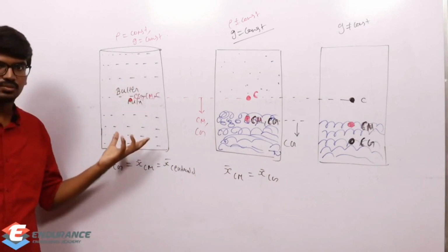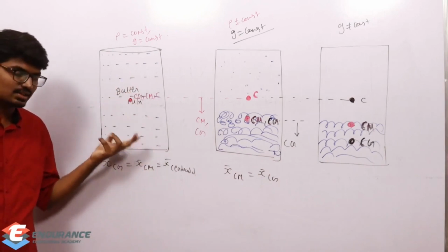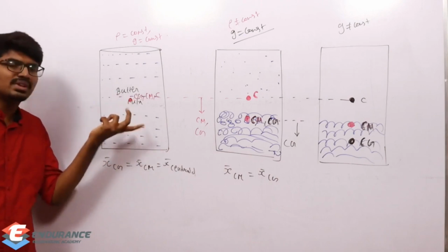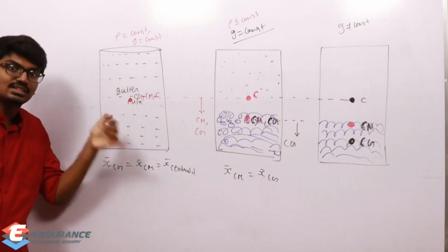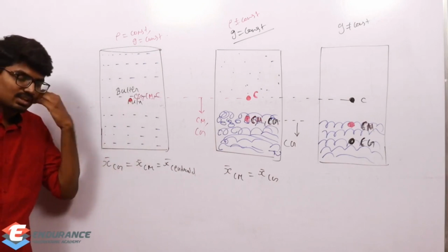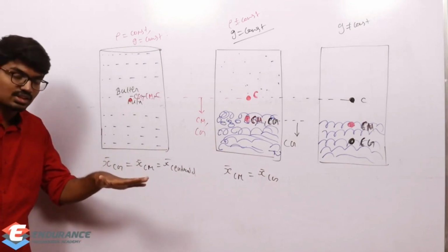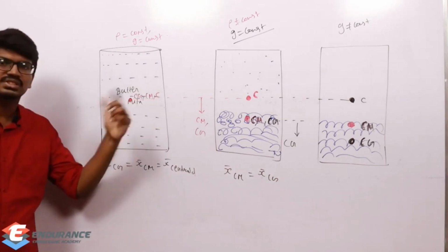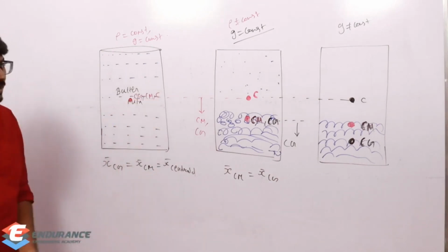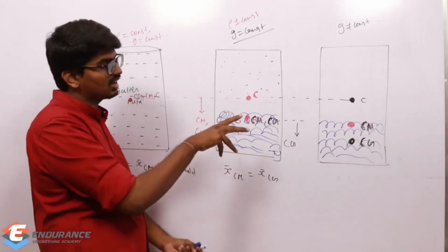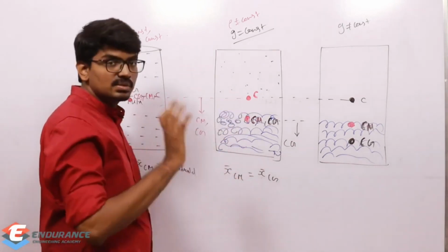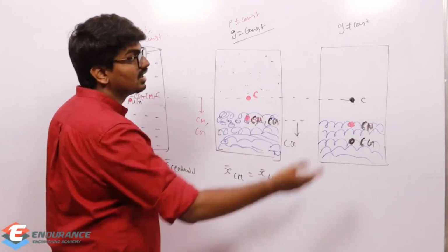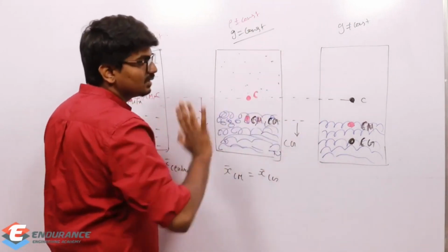If it is a homogeneous body, if density is constant and acceleration due to gravity is also constant, then all three will be the same. So during that time, where density is the same and acceleration due to gravity is also the same, all three will be at the same point. So using the terms interchangeably is not at all a problem. But if density varies, then using the terms interchangeably will be a problem because the centroid is different. Now the center of mass and center of gravity are different. If G also varies, then all three will be different.